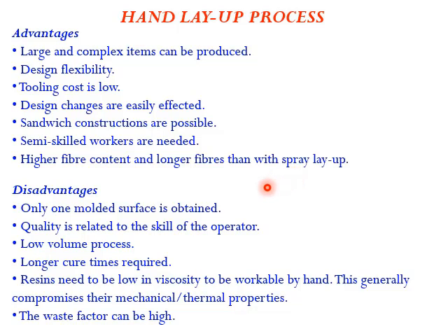So what are the disadvantages? Only one molded surface is obtained. Quality is related to the skill of the operator. Low volume process, longer cure times required. Resins need to be low in viscosity to be workable by hand. This generally compromises their mechanical and thermal properties. The waste factor can be high.